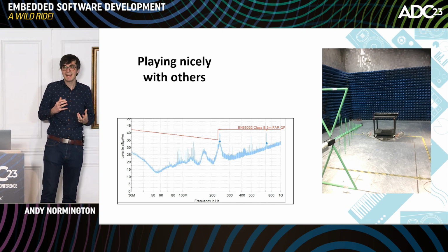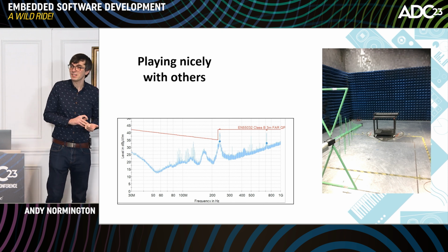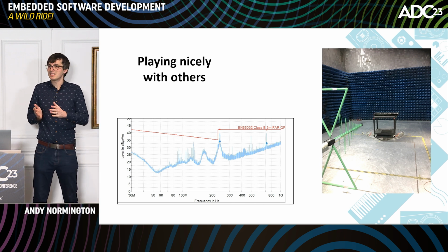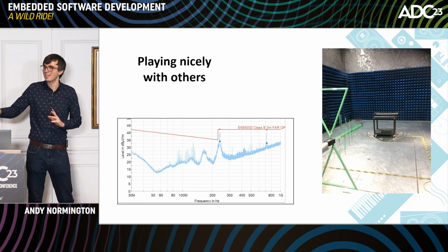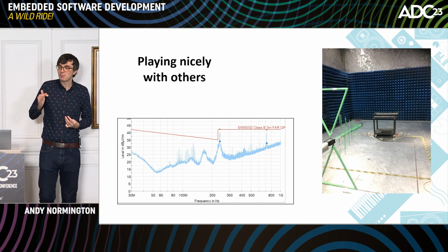We can look at the pinout that we chose early on with the electronics engineer, and we try and plan for that so we don't have to make changes to this later on. That can help us to keep sensitive signals on long traces away from aggressive signals that are going to cause the noise problems. We can look at how hard we're driving signals.